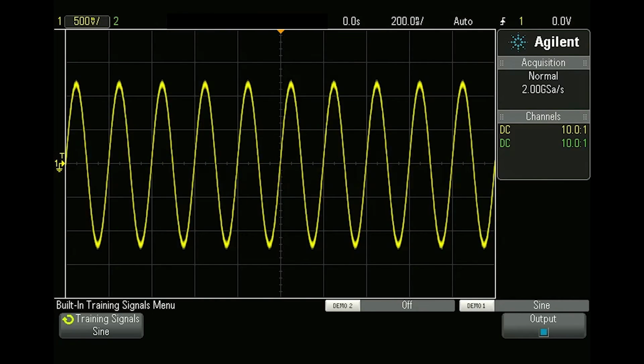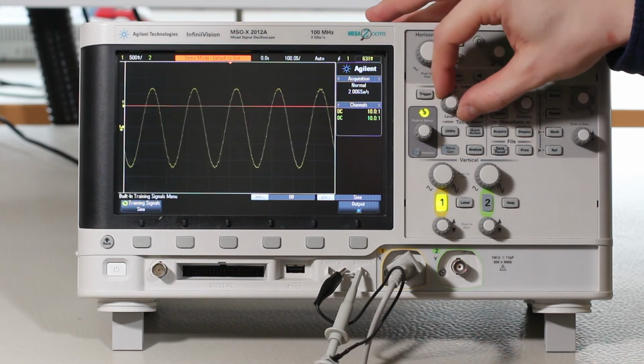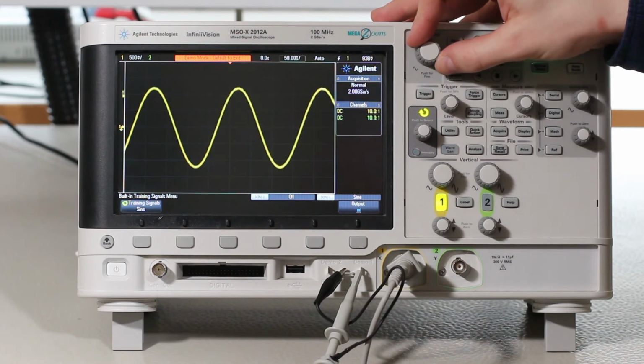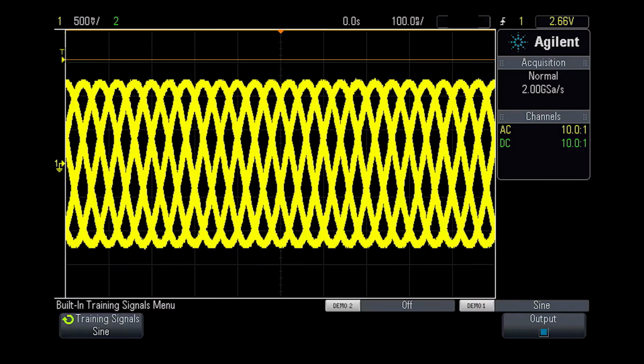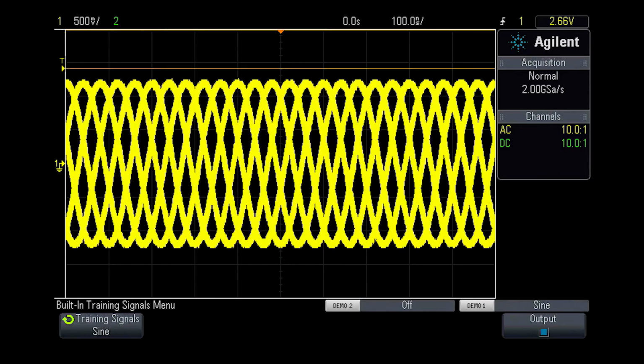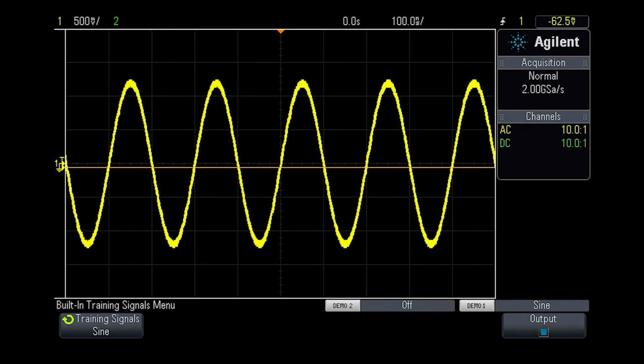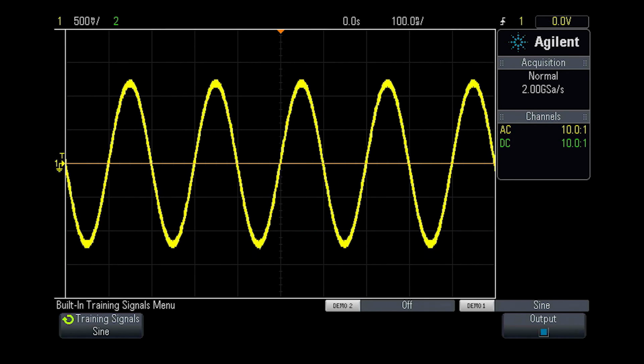The next common feature to oscilloscopes is the trigger adjustment. Basic triggering is used in 2 ways. It can be used to synchronize a repeating signal so that it appears static. The trigger dial changes the value on the upward or downward slope of the signal that is used to synchronize